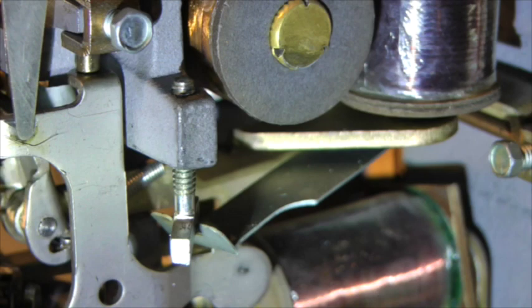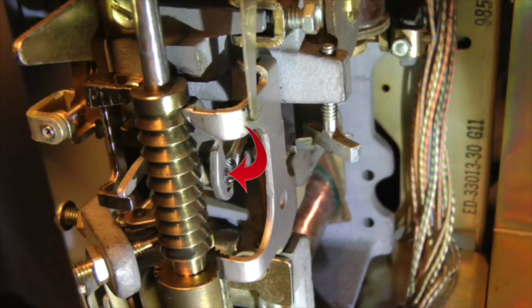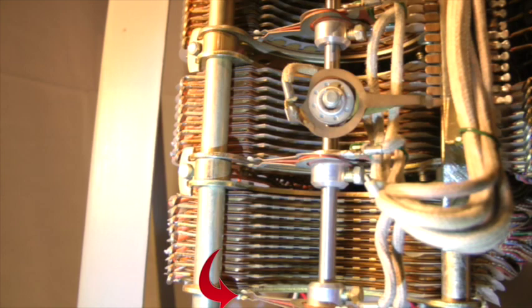With both the A and C relays operated, the energizing path for the vertical magnet is closed, and so the vertical armature operates. The vertical pawl engages the vertical ratchet and steps the shaft and all of its attached apparatus vertically upwards by one step. All three sets of horizontal wipers step up one position so that they are in line with level 1 of all three bank tiers.